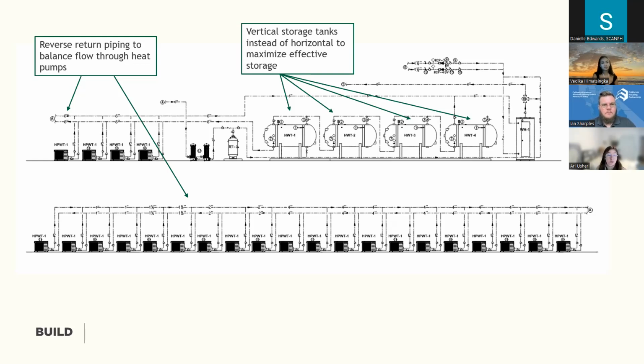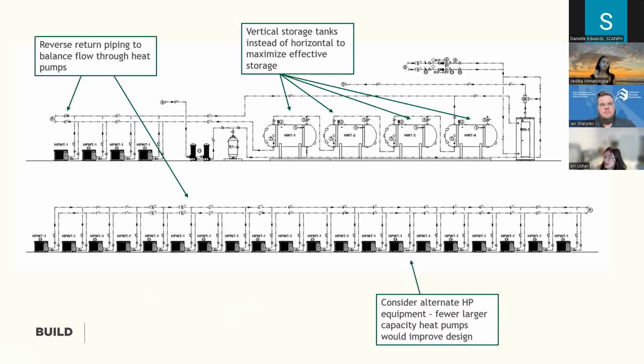And that's going to reduce the overall efficiency of the plant and also cause quicker wear and tear on those first couple of heat pumps. So, showing reverse return piping in the diagram here is going to give you the best chance to have that reverse return piping, a little bit of a tongue twister, installed on the project. And then finally, Vedika mentioned, alternate system recommendations.